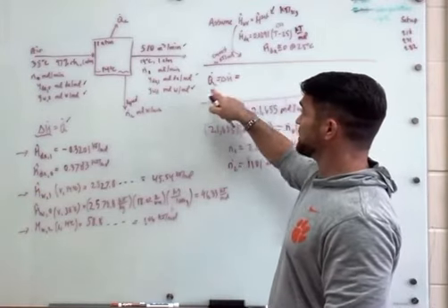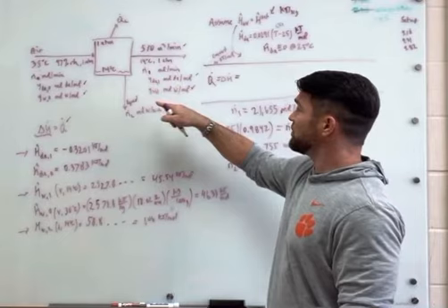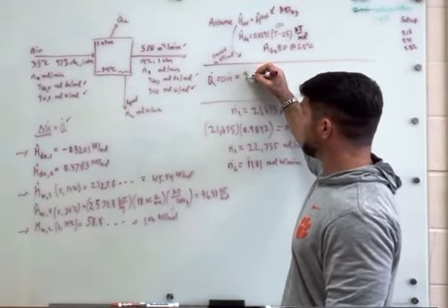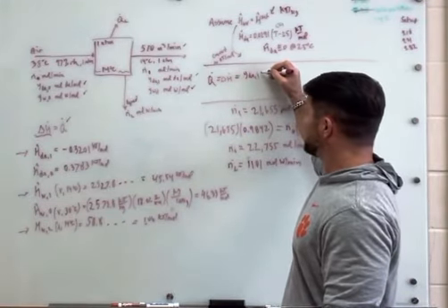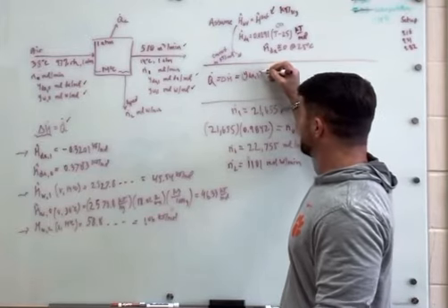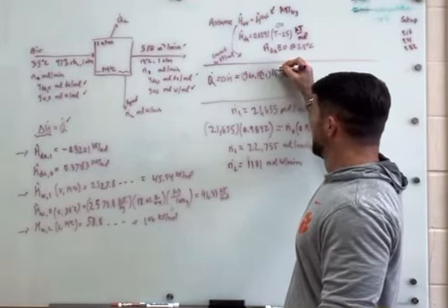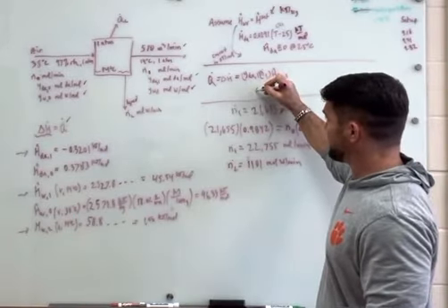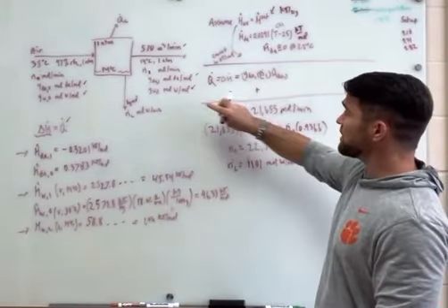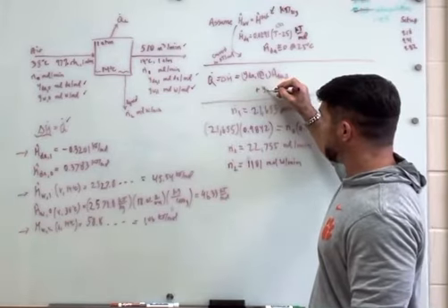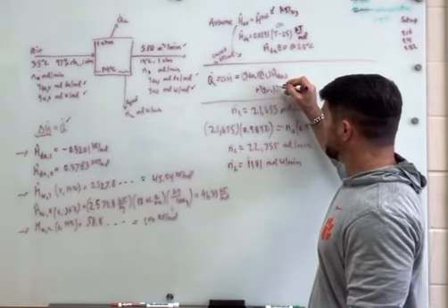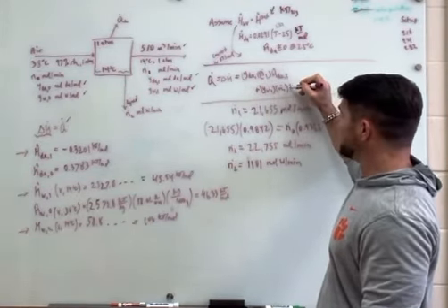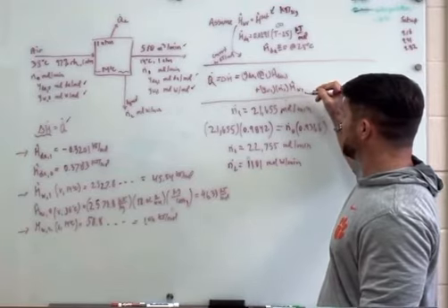So let's just look at what these are. Coming out, we're going to have the moles of dry air. So the moles of dry air coming out are going to be y_dA1 times N1 times H dry air 1. Plus, and I'm just going to write these down here, I'll show you why. The water coming out is going to be y water 1 times N1 times H water 1.